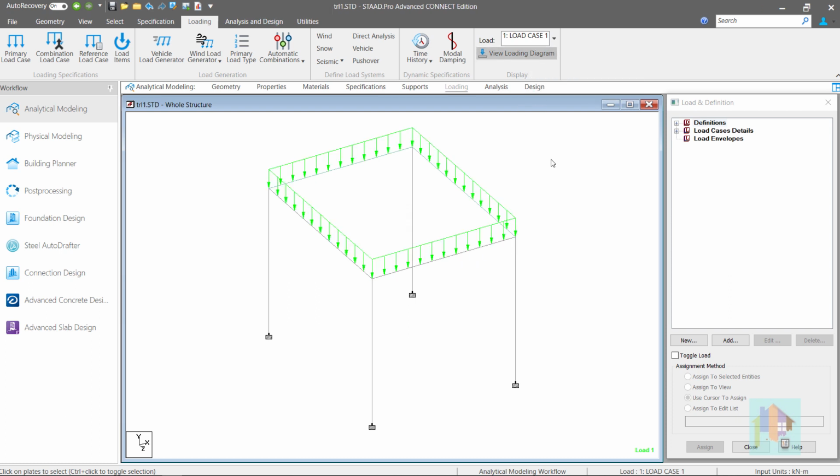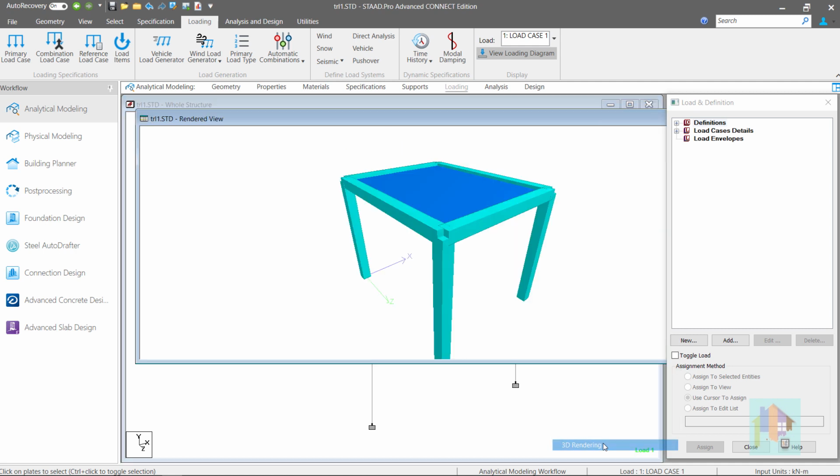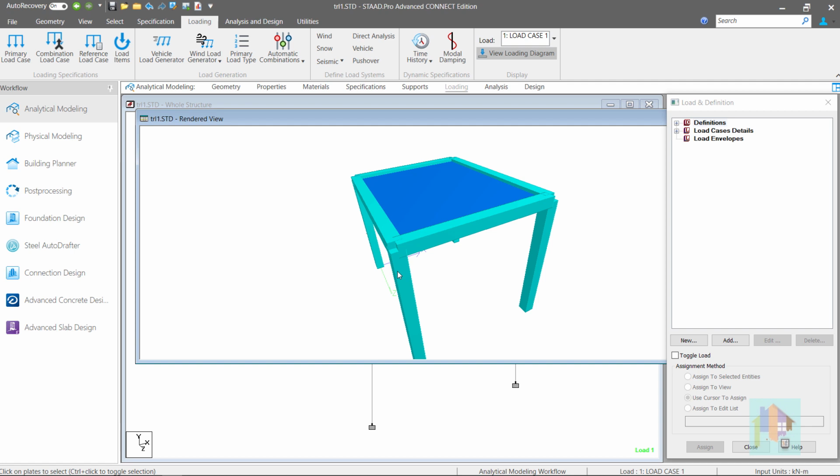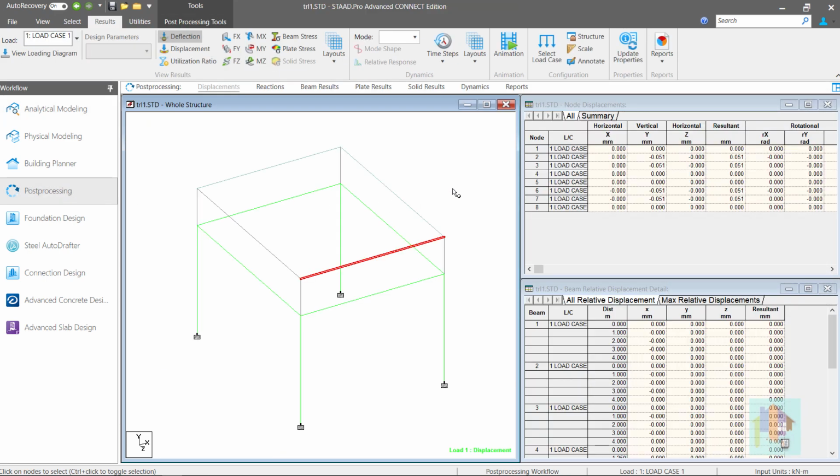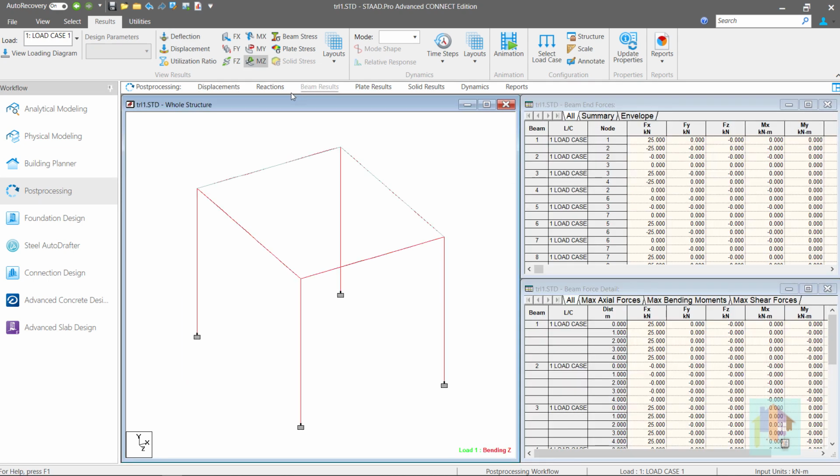As an example, I have used this tabletop structure with a single unmeshed plate to replicate the beam slab interaction. This plate does not have intermediate connections with the beam, hence no force is transferred to the beam from the slab. There is no support at the plate edge and it just settles due to the applied load, resulting in zero moment and shear in the beam.